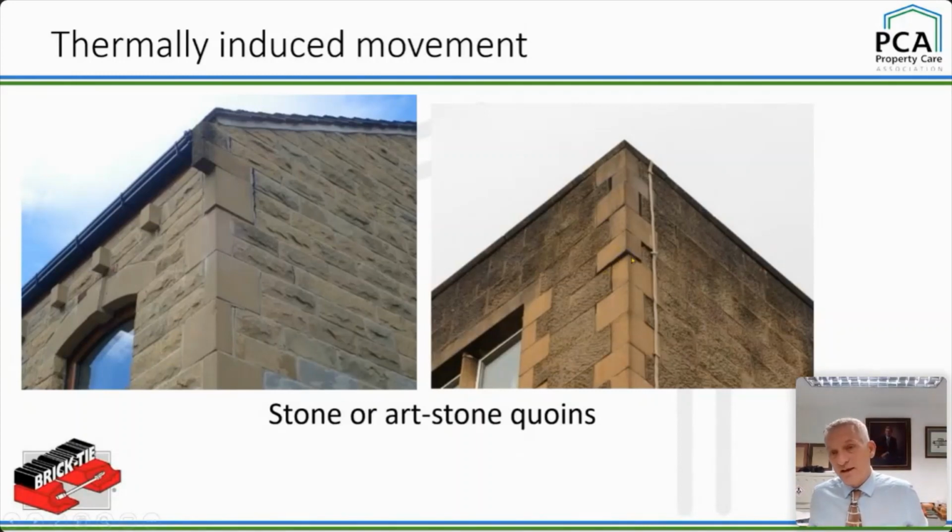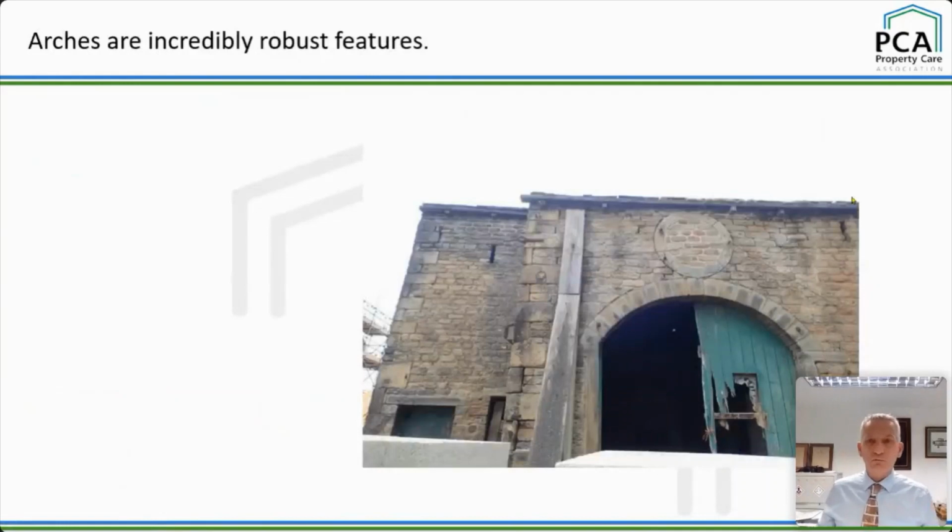That overhang there, remember that 3 stories up, that overhang is about 40 mil, but I've seen them with greater overhang than that. All right, so that's why you ignore thermal movement at your peril. It can really come back and bite you.